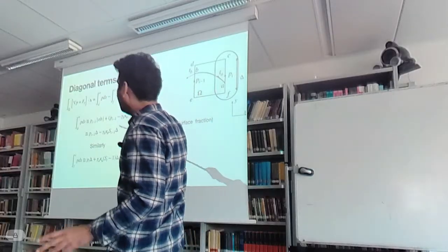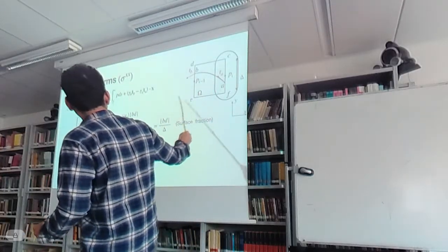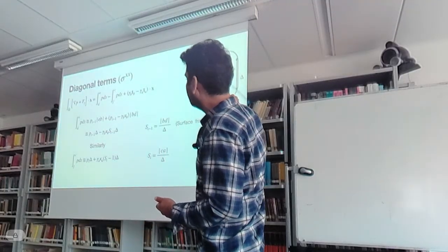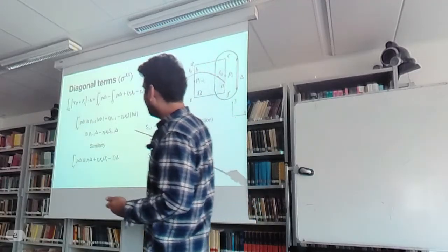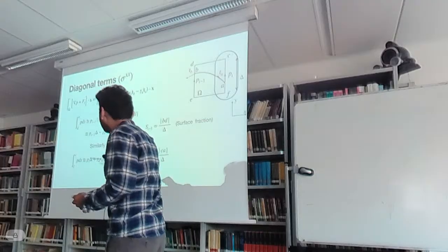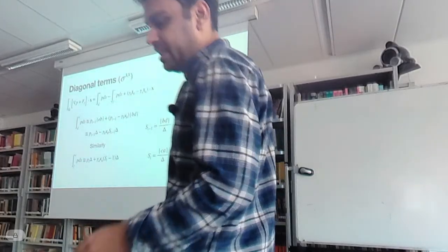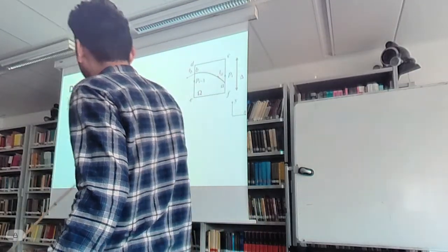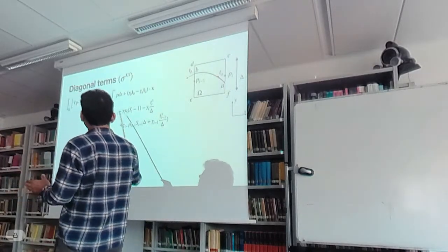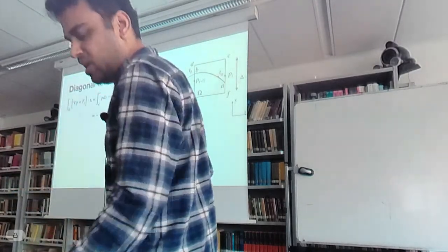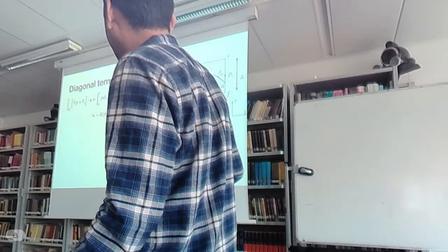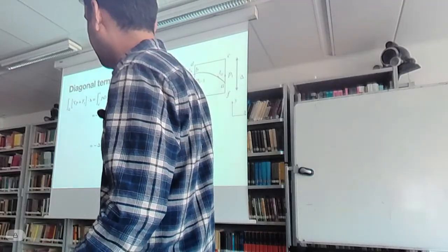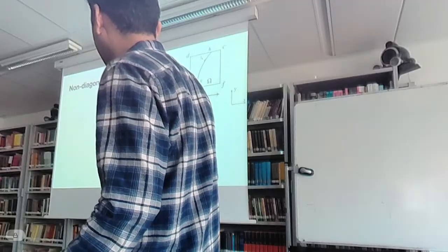And this you can generalize by defining surface fraction. So it is nothing but the fraction of non-reference phase that is wetting the cell phase. So if you do this, you can write this contribution more generically, and you can put this back in the equation on top, and you can isolate the pressure part and the part that appears due to the surface tension, and you can write this as the difference in the diagonal terms or diagonal elements of the stress tensor.